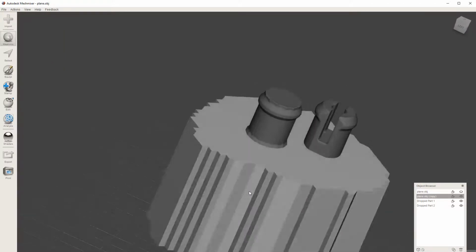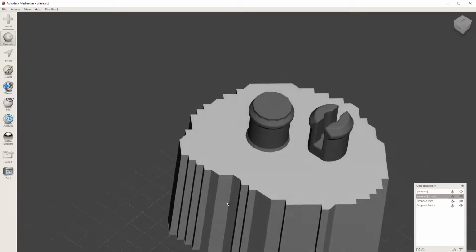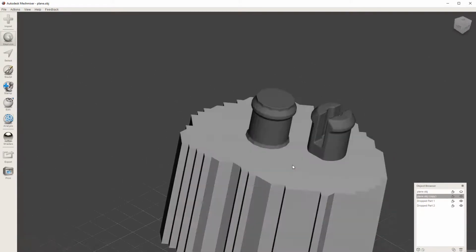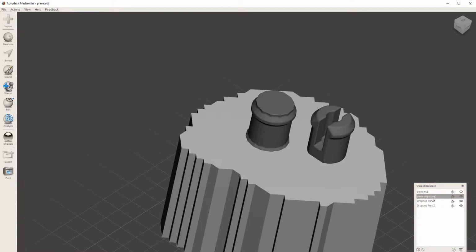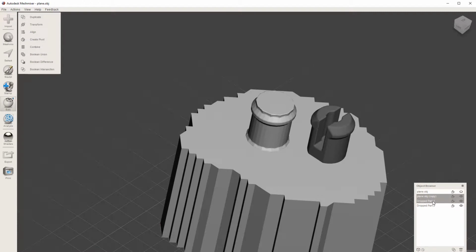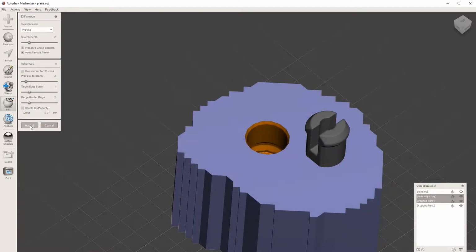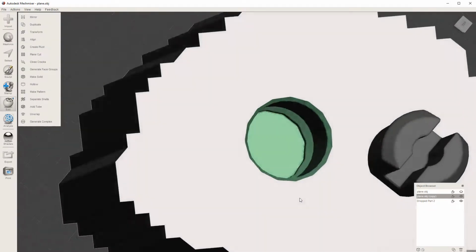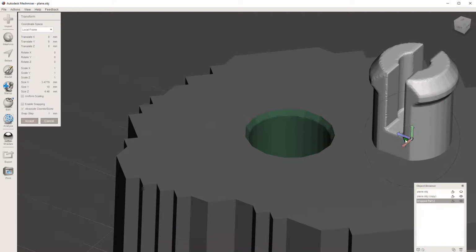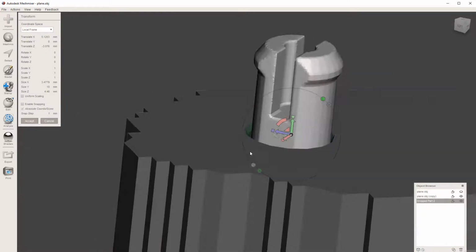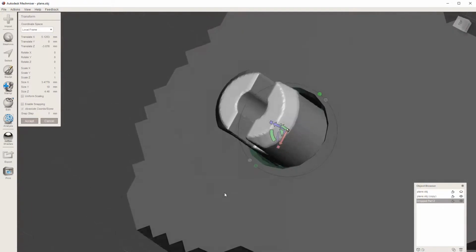like that, we have these pins in here. Now obviously what you can do with this is pretty easy. We have our pins right here. Select this one and this one, holding down the control key. I made sure to select the second one, the pin part, second, and then just do a Boolean difference. And what that will do is cut that hole in here. Now, because I sized these in the same way, if we move this over, you see that there's a gap around the edge.